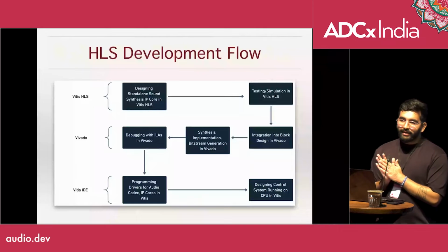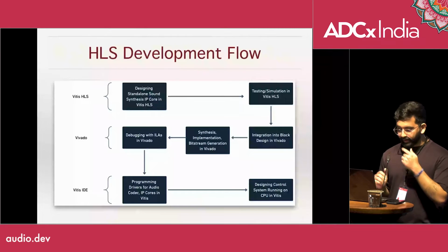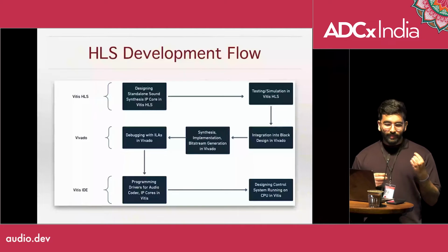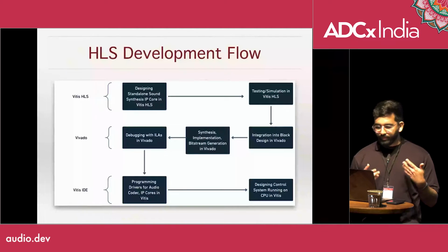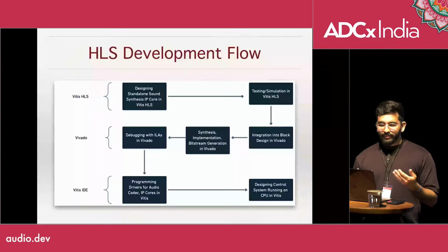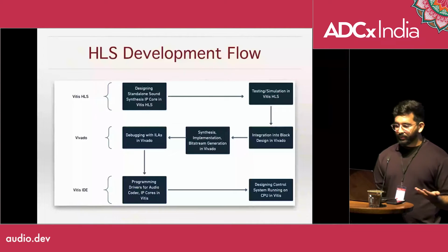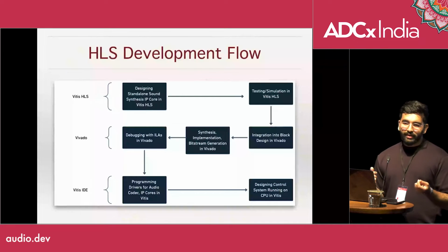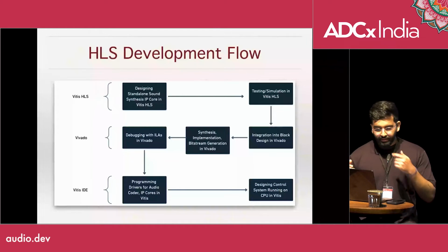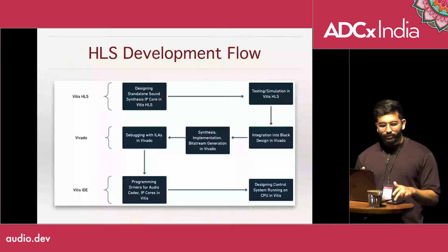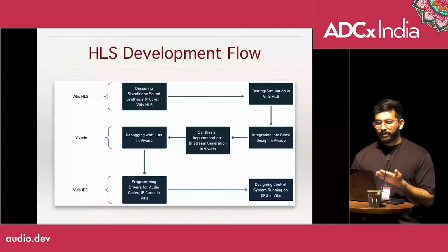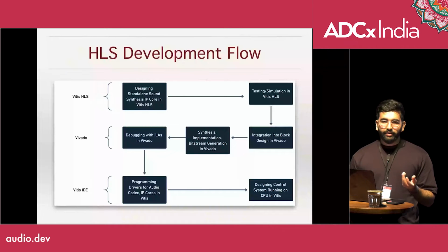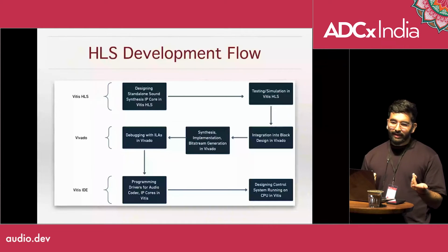Like I said, traditionally, FPGAs were programmed, and are still programmed, with very specific hardware description languages, which require specialized hardware knowledge that is beyond my scope as well. And it's something that is not generally in the scope of the audio developer or community. So HLS provides some mitigation of that issue to some extent. With HLS, you have a C or C++ program that gets converted into the hardware code. These are automated tools that are provided by the vendors. Xilinx has them, Intel has them as well.